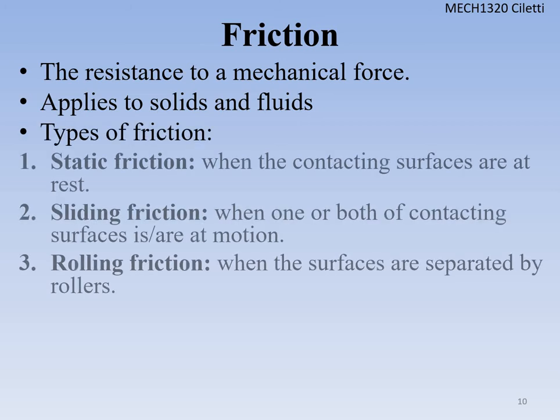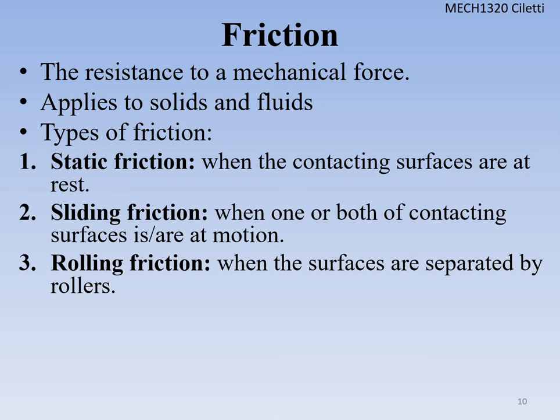Okay, so there are different types of friction that we can talk about here. Three main ones, right? Static friction, when the contacting surfaces are at rest. Say you take two things covered in sandpaper with a really rough grit on it. It's going to be hard for you to move that because it's trying to grip. Or you take something rubber coated and try to slide it across a basketball floor. It's really hard. Both of those contacting surfaces, if you start them at rest, are not going to move around too much, okay? But it's hard for you to overcome that friction, right? Because that rubber has a higher coefficient of friction than the floor, so it's going to stop you from trying to slide the ball or slide your shoe when you're running and you want to stop.